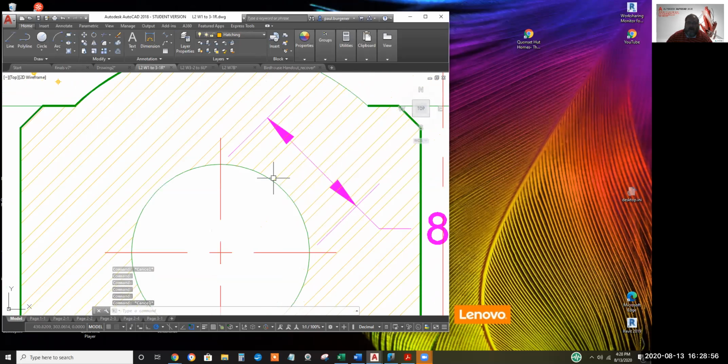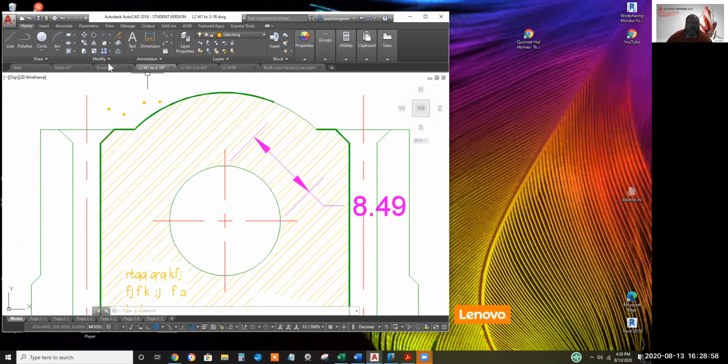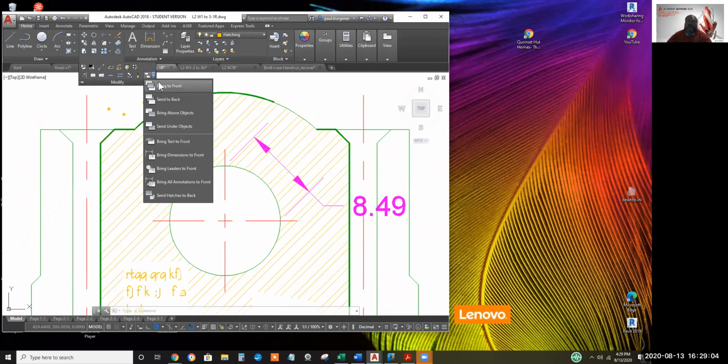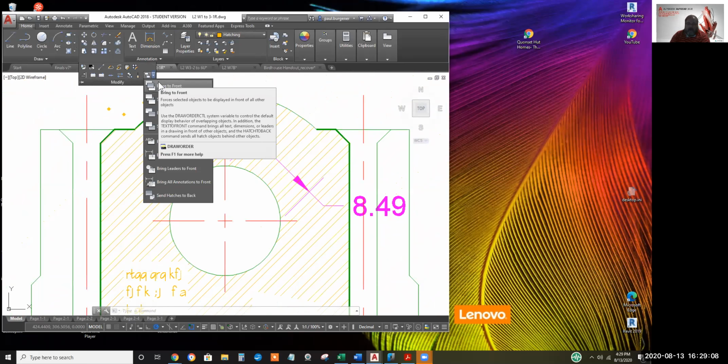Orange prints out. When you get into the solid fill crosshatch pattern, be ready to use this draw order, because like say you put the electric lines over the tennis court and then you go to solid fill. Anyway, you generally want your solid fill to be in the back, your dimensions and notes to be in the front.